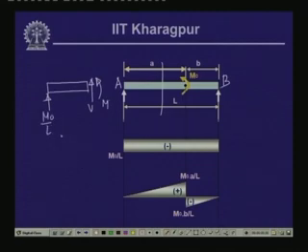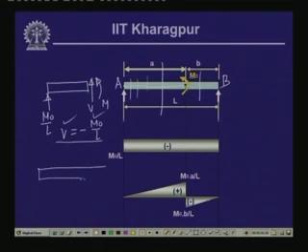So, summation of vertical forces will give V as equal to minus M0 by L. So, the value of the shear force at any point between the segment from here to here is not a function of x, it is a constant. Wherever we take the section, we will have the value of shear force as M0 by L. Now, if we take a free body at this particular segment, the free body becomes like this: we have the reactive force which is M0 by L, we have the concentrated moment in an anticlockwise direction, and we have the shear and the bending moment.